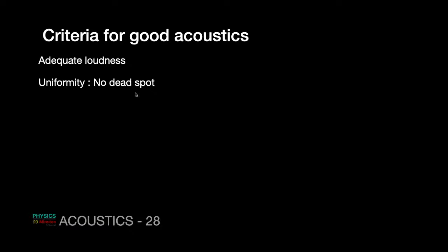Dead spot means there shouldn't be any spot where no sound is there, maybe because of destructive interference, maybe because of a shadow, etc. No such spot should be there in an auditorium anywhere. Clarity: different instruments, different words, when they are spoken, should be heard properly and deciphered properly by the audience. If that is not happening, that means there is a loss of clarity.